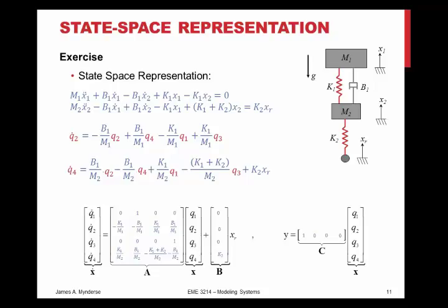Is this better or worse than transfer function form? Well, it's just different. It allows me to see what's going on internally, so that if I wanted, I could look at both the motion of the tire and the motion of the driver. Is it easier? Is it less easy? Well, it depends on how you like to do Laplace transforms. Notice there's no Laplace transforms, it's only derivatives, but I do sometimes have to do a little finessing to get them into first order ODEs, especially if you've got a much more complicated and coupled system. We'll see some examples of those. But this is state space representation.